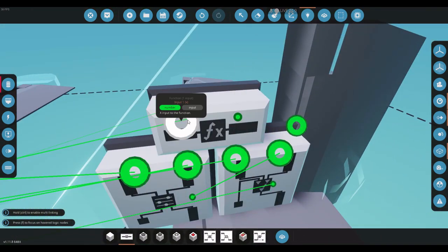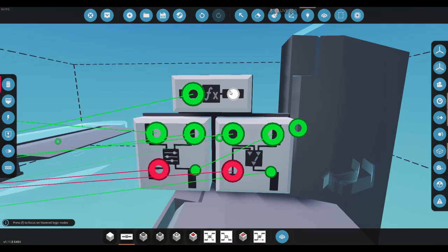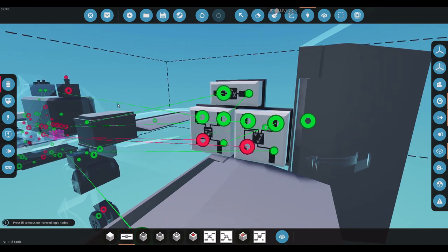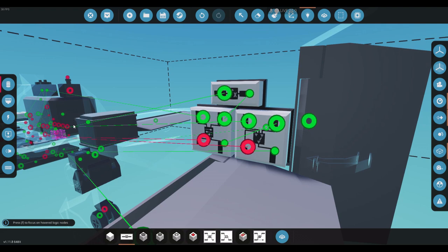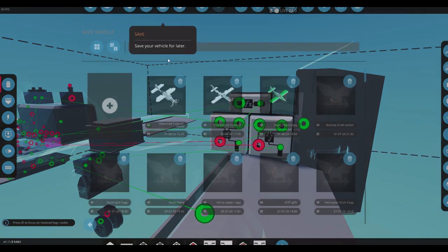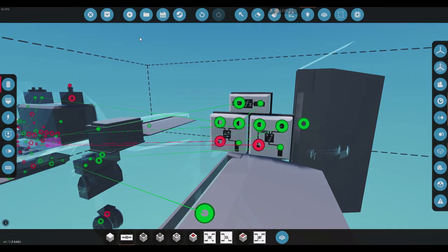We're going to put it into the function where it subtracts that value, the difference, and that's going to be our new PID set point. Here's the PID set point. So there we go. So now we take in our keypad. Whatever you put in the keypad, it's going to automatically subtract 5 and put it into there as the set point. So that works like that.